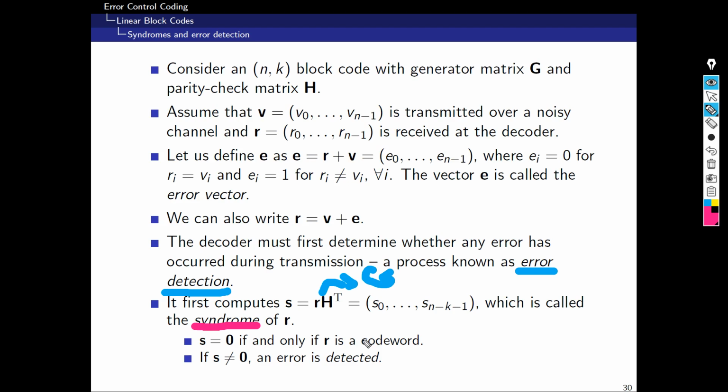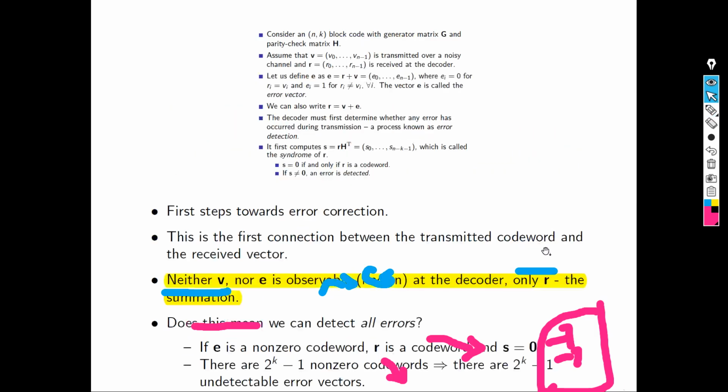Okay? So this we call it an absolute error, because you are detecting a code outside of the range of codes you used at the transmitter. And in the other case, you detect a code among all the used codes at the transmitter, but you don't know which one is really the correct one. That's why we move on to the other steps that can help us determine this.